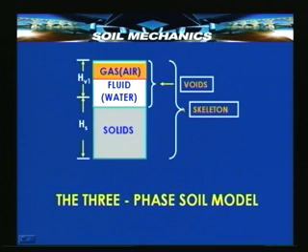Now, this combination of solids, any fluid that occupies the voids and any gas that occupies the voids, or in other words solids plus the voids together, the total soil is called the skeleton of the soil. The soil skeleton includes the solids, the fluid or the water, usually water, and gas, usually air, in its voids, and this 3-phase model forms the very basis of illustrating and understanding how time dependent compression takes place in soils.